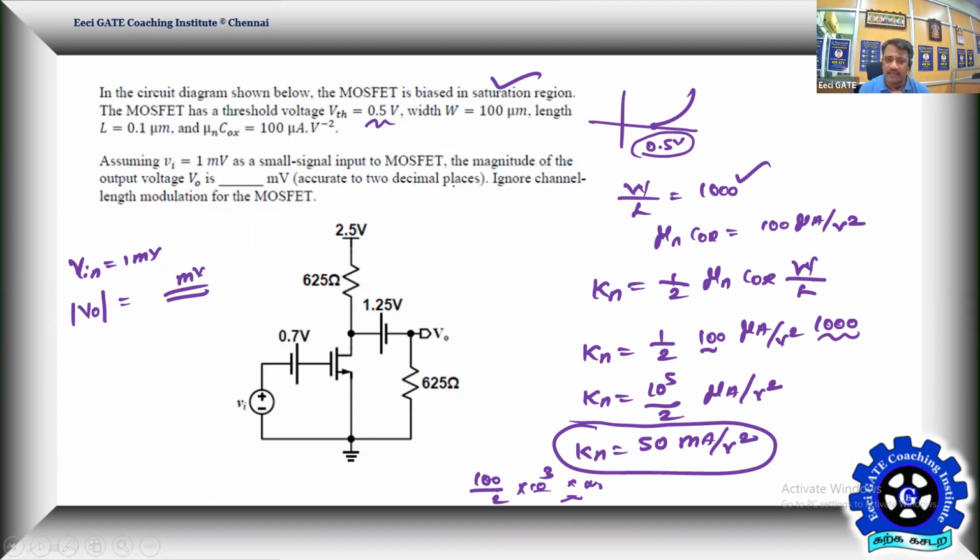Fine then. In fact, this is a little easier than the GATE 21 biomedical paper for NMOS. Yes, we have to do the DC analysis. There is no other choice. We have to perform a DC analysis, so you have to switch off the AC signals. At the end of the DC analysis, you need not prove that it is in saturation, but we need the channel current IDQ. Once IDQ is known, we can comment on gm. So what is your current ID when the device is in saturation? ID is equal to Kn into VGS minus what?